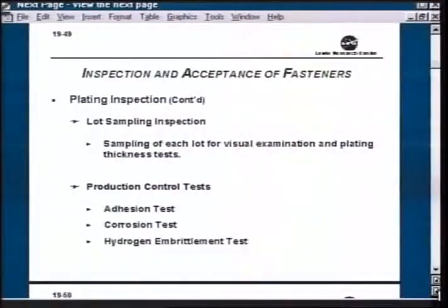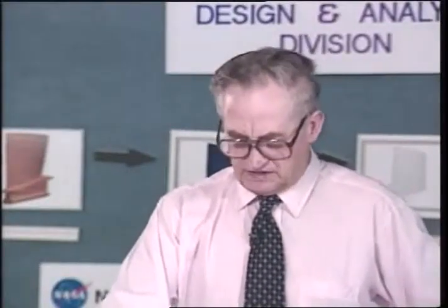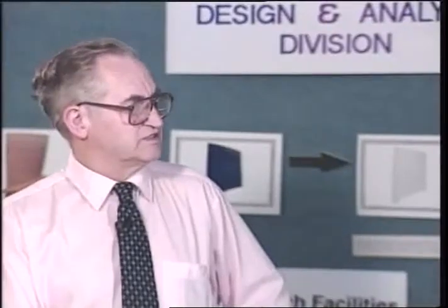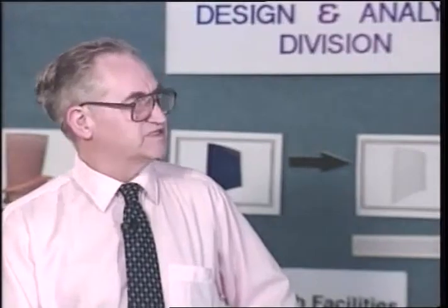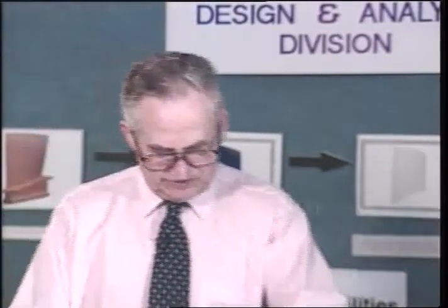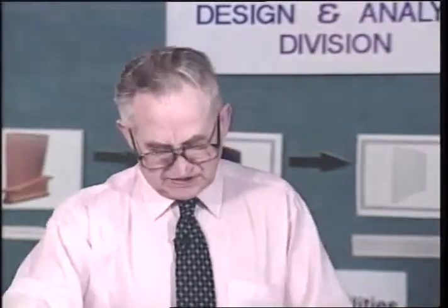There is, in fact, I believe a guy from here at Lewis just recently developed a method of inspecting the thickness of plating. Dan Roth works over in the M&S, or what used to be M&S, I believe, developed one. But there are methods of looking at, and I think ultrasonically measuring plating thickness on materials. You can do an adhesion test, you can do a corrosion test, and you can do a hydrogen embrittlement test. Although the hydrogen embrittlement test, you can get that with both zinc and cadmium, so that in itself would not be conclusive.